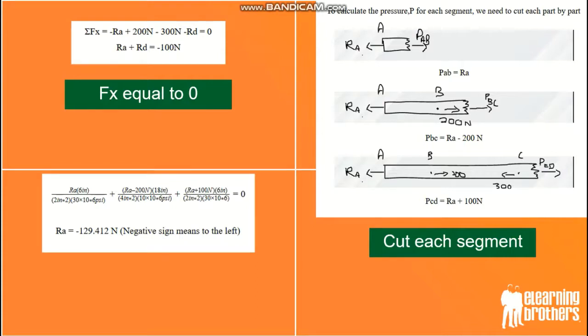Alright, so next, from the information from all the internal forces we get, we use the formula mentioned here. It is P times L divided by cross section area times E, or the Young's modulus, summed over all of the segments and equal to zero. Equal to zero because the bar will not change in length because the door will not move.